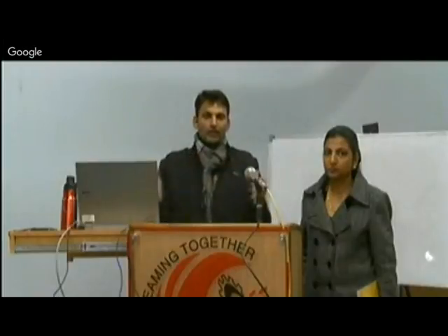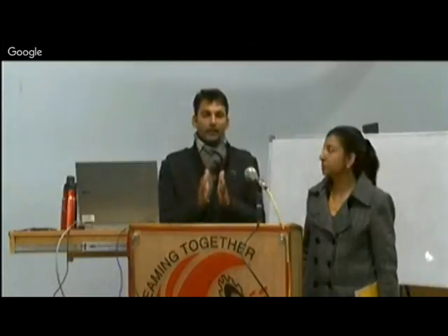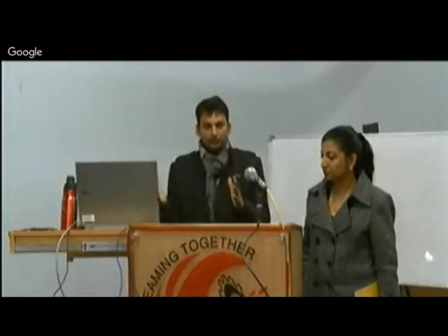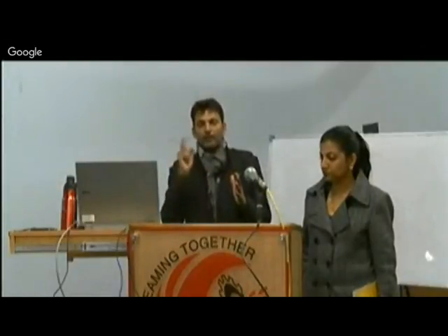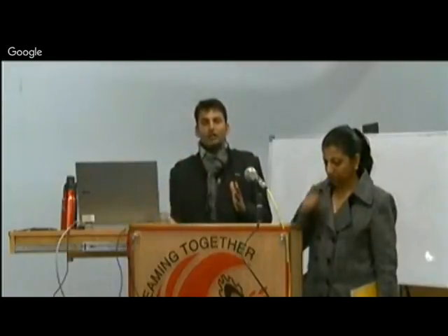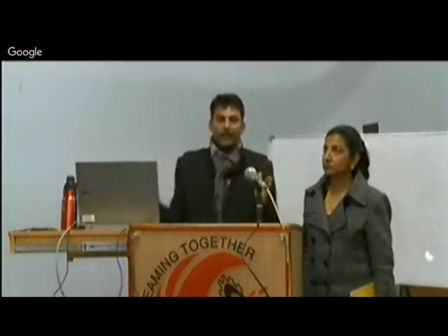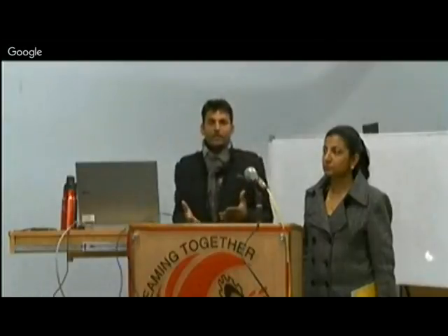The Wenner array is nothing new, but we combined the Wenner array, Schlumberger array, dipole-dipole array, and inverse Schlumberger array. All those combinations, we created a special design array in which, just by using 7 electrodes, we are able to get information from inside the soil, about 30 centimeter, 50 centimeter, 60 centimeter. We can scan different layers of the soil horizontally, in different planes, using this kind of sounding depth principle.